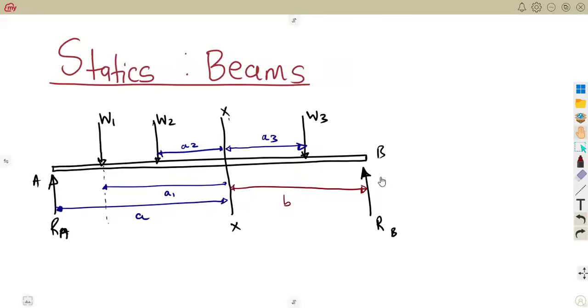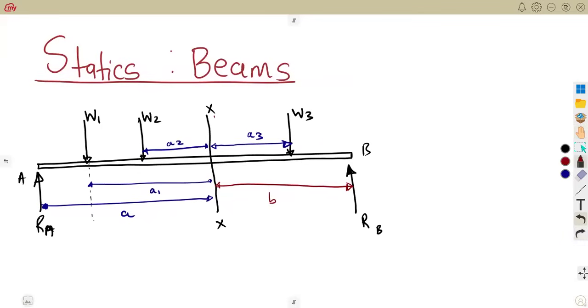All right, so let's have these two guys in view, because like I said, remember when you're determining the shearing force or the shear force, if you're at this point, you consider, okay, you're starting at this point. Which forces do you have there? You take all the forces that you have on the left side of that point. Meaning to say, we do not have anything. We are going to take it as a 0.